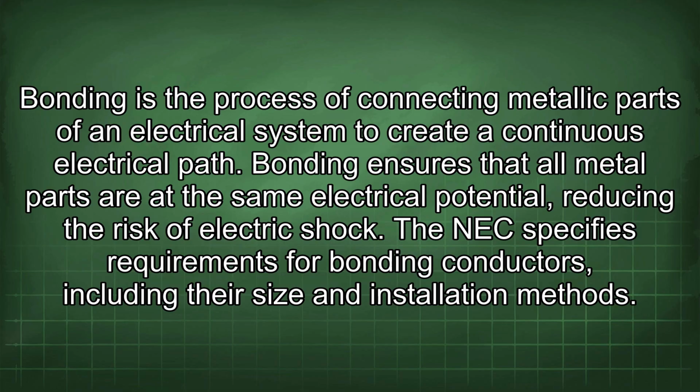Bonding is the process of connecting metallic parts of an electrical system to create a continuous electrical path. Bonding ensures that all metal parts are at the same electrical potential, reducing the risk of electric shock. The NEC specifies requirements for bonding conductors, including their size and installation methods.